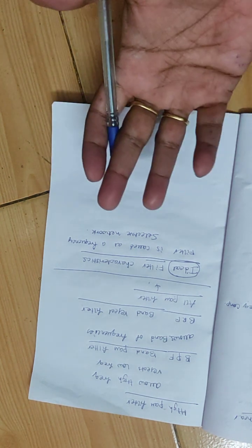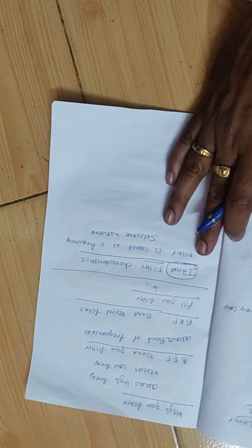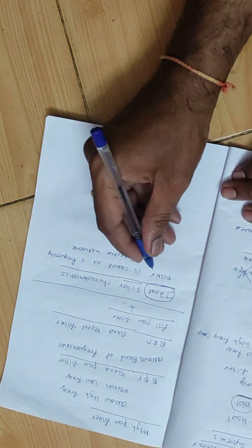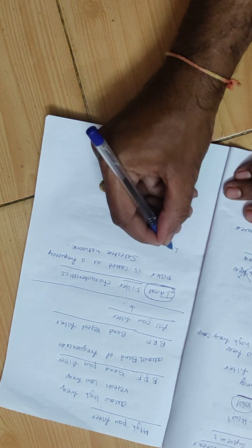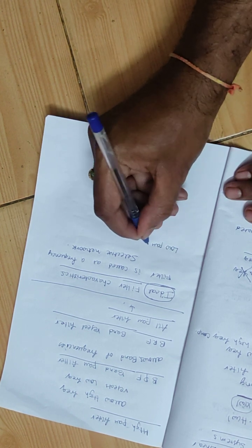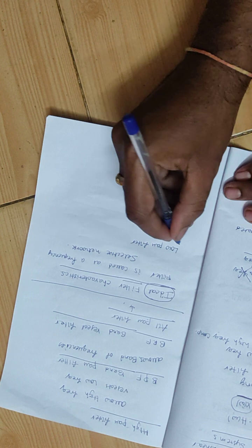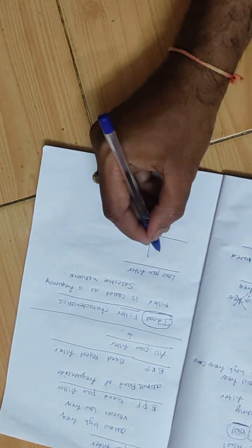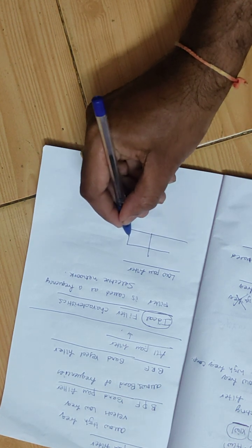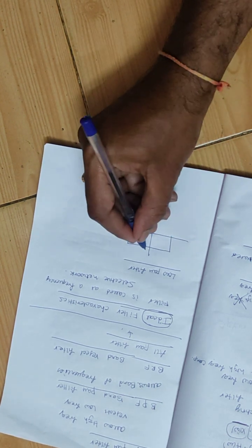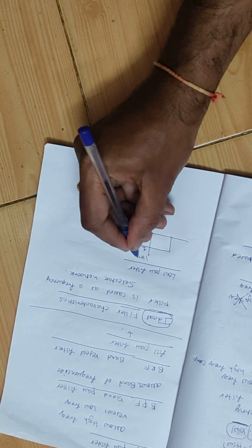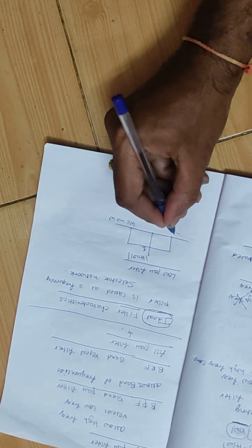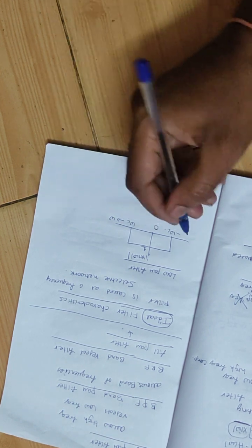Okay, then what is an ideal filter? An ideal filter is something which has a sharp cutoff. Let me draw the low pass filter. An ideal low pass filter will have a frequency response like this. See, if you carefully observe, this is 1 and this is modulus of H of omega. This is omega. So this is omega c, this is minus omega c, this is 0.